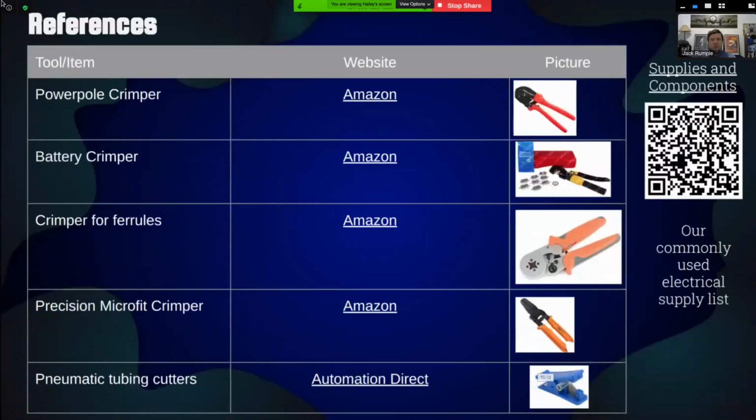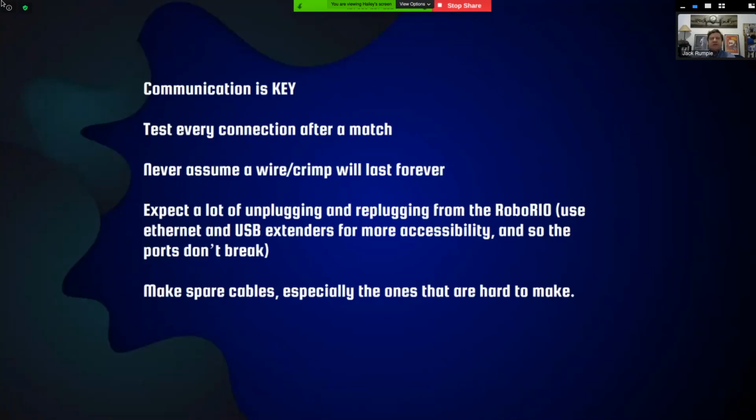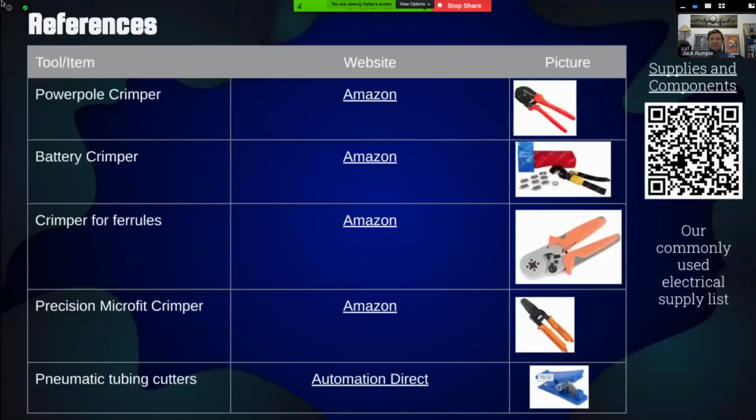So one that I would add to that is, after you've got your superstructure or your mechanism on, double check the ease with which you can get your battery in and out. We've had a couple times where that wasn't considered, and it was a bit of a maze or Tetris to pull and replace batteries between matches. Definitely.